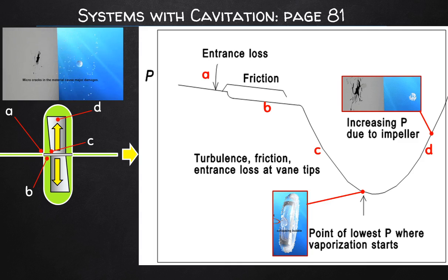So there's usually a vacuum that's created before it leaves the impeller housing, where the pressure is increased much higher than what was behind in the suction line, in the upstream pressure. It is at this very low pressure condition where cavitation might occur if the liquid is close enough to its bubble point, or even if the pump is powerful enough to induce such low pressure drops that the pump itself induces cavitation irrespectively.